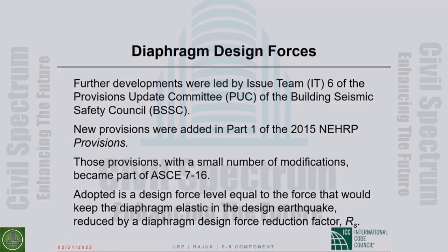Okay, doctors. To design a diaphragm, you mentioned only shear walls, but for columns, does the design procedure differ, or is it the same? It's just a diaphragm typically won't sit on columns. It will sit on frames. Okay, and the shear transfer will be the same. It will go to the beams of the frame. Okay, and if it is high seismic, you cannot have flat plates as part of the resisting system, I told you. So you will not have a slab sitting on columns.